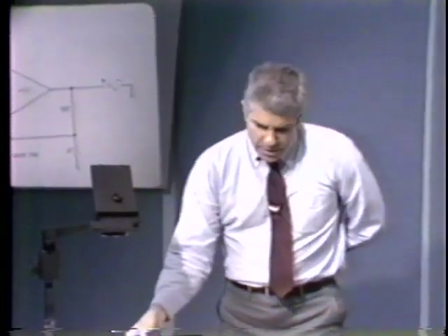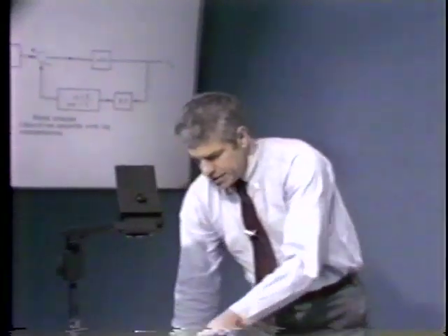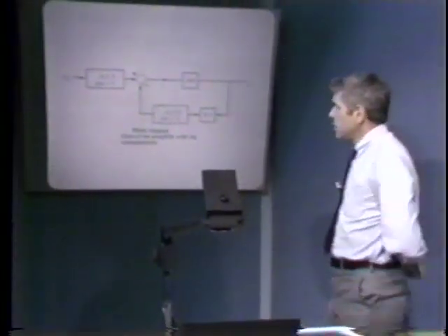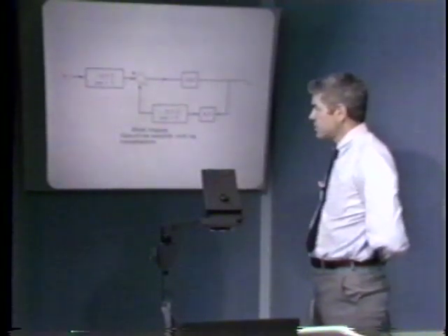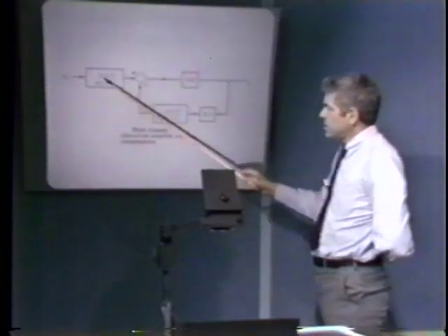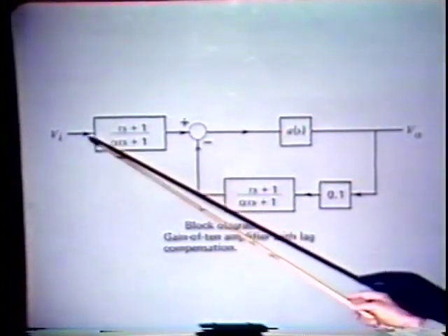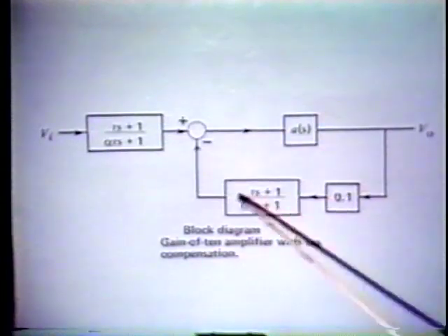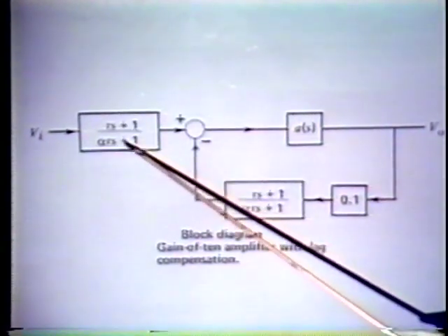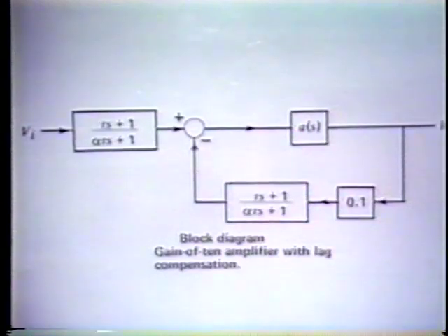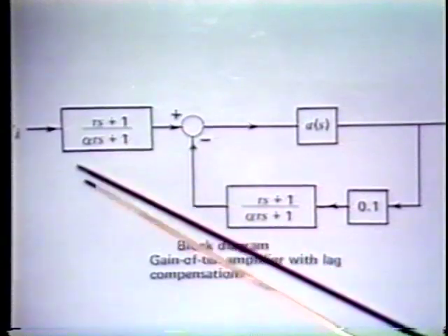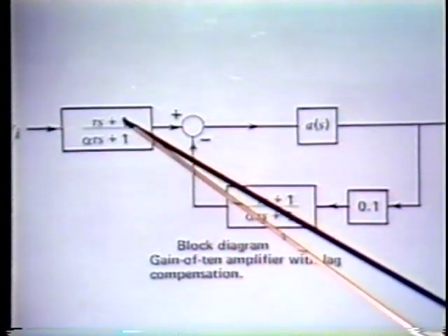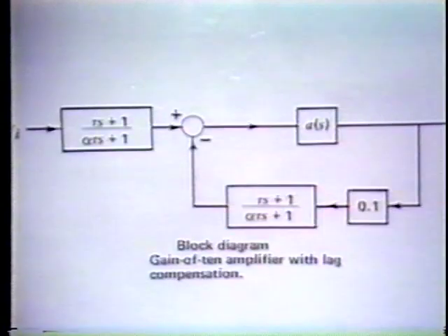The effect on the block diagram for the amplifier is as follows. This parallels very closely what we did in an example, I believe two sessions ago, where we put a resistor between the terminals. We found out that that resistor provided an attenuation to the input signal as well as to the signal fed back. Here, because we use an RC between the input terminals, we get an attenuation, or a lag type transfer function, applied to both the input signal path and the feedback signal path.